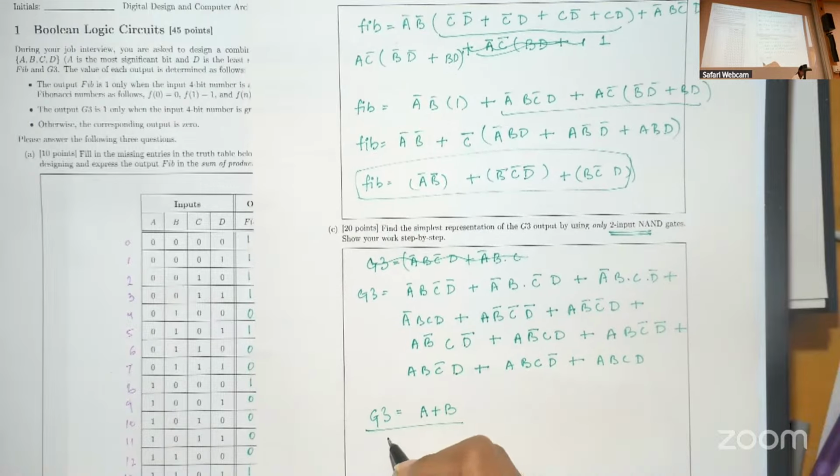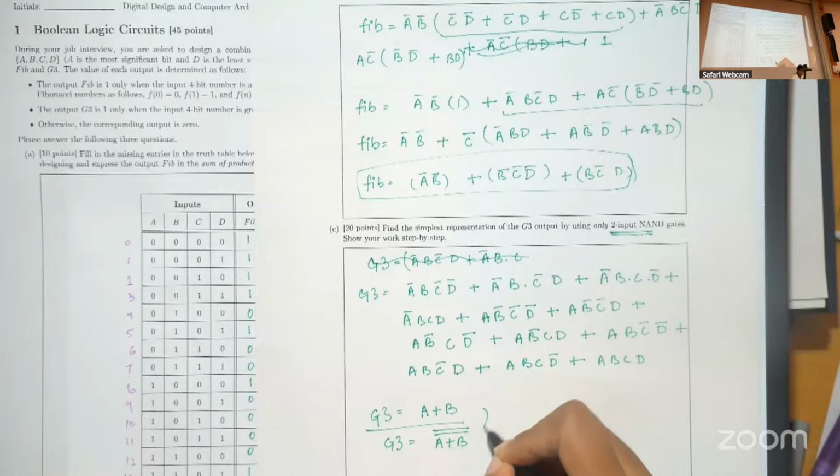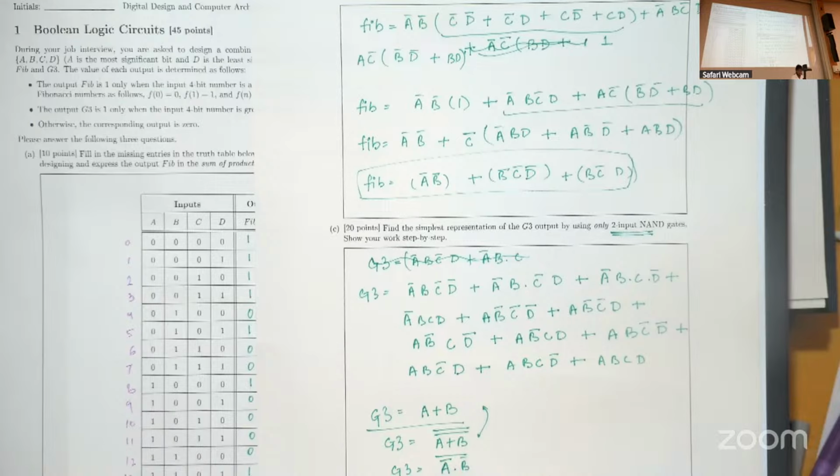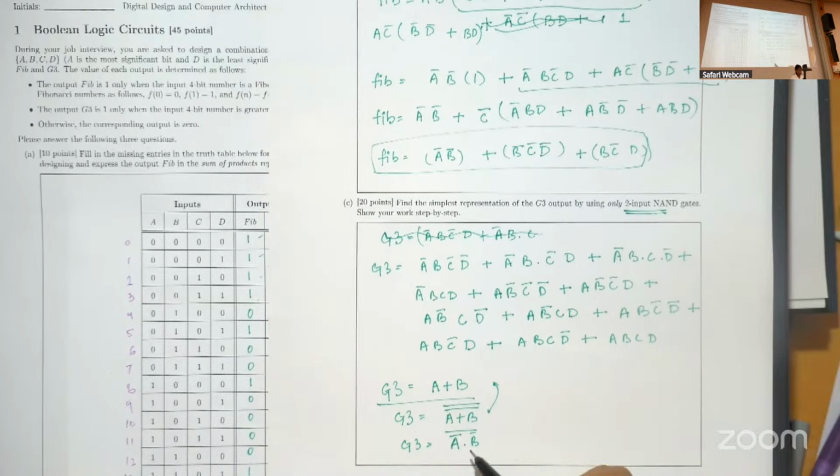So since we want NOT, because NAND has NOT and AND, we can start by taking the NOT of this. And if we write it, then these two are equivalent terms. You can also write this as the complement of A, like this. So you can also write this as this, but now it has 2 NOT gates, and we do not have any NOT gates. We only have NAND gates. So you can also write this A bar as A into A, the whole bar.